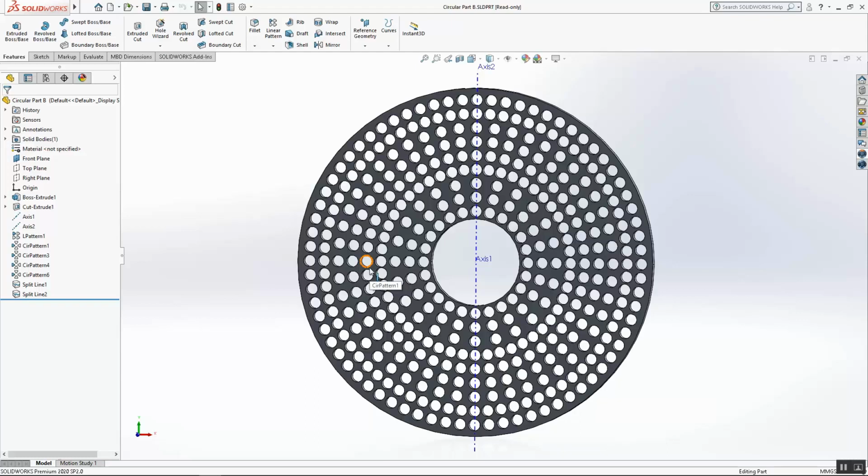So that could be a lot of contact pairs, depending on how much displacement we're applying, depending on how compliant our material is. And if we're trying to correctly size this to be able to withstand a certain amount of rotation or a certain amount of displacement, maybe we need to play with the number of holes, the size of the holes. It could get relatively complicated. So the SIMULIAworks tools basically use a completely different approach to handling contact. And we'll talk about that in both examples, that there are some really unique things that the SIMULIAworks tools can offer us.